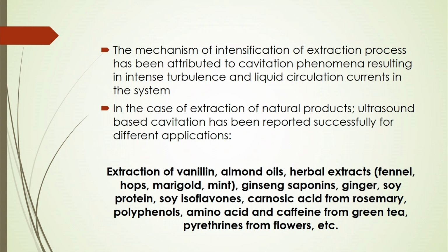intense turbulence and liquid circulation currents in the system, based on which you can intensify the distribution of the energy to produce finer droplets through the packing material, as well as in other systems. But based on this cavitation process by ultrasound, you can work without packing, more intensely, because if you are using packing materials, some other frictional resistance will come, because of which some extra energy may be required to produce the droplet.